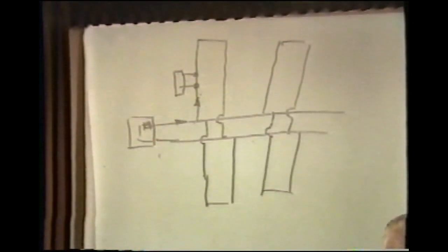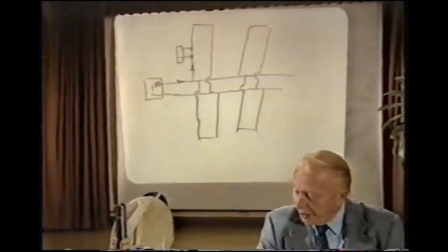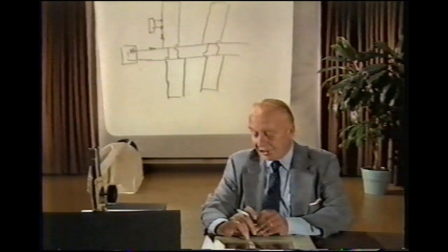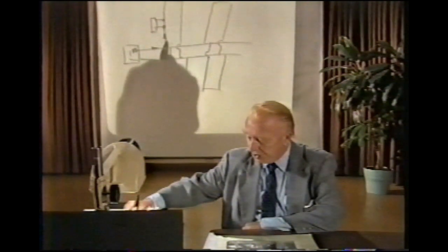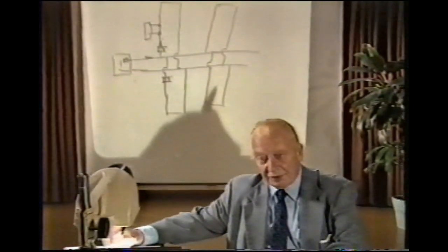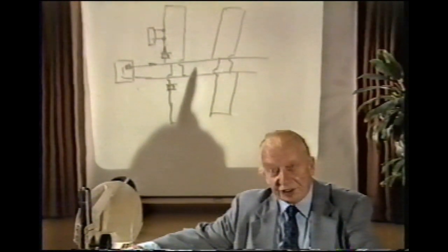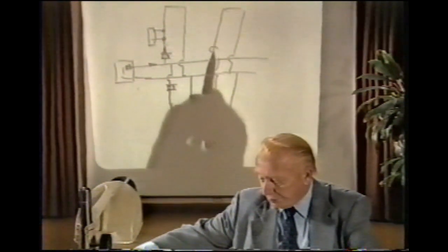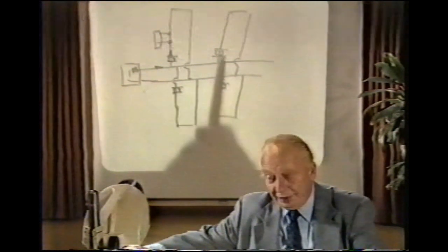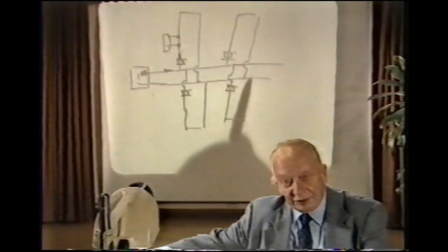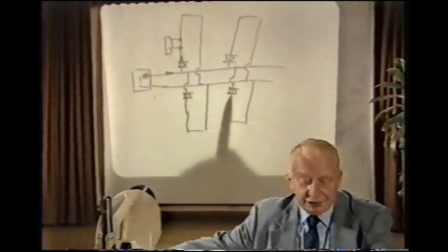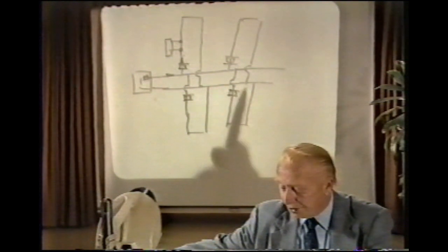Well, this developed into a very substantial problem. And the solution was very difficult, or we thought so at the beginning. Our first thought, of course, was to simply place extra pumps in each of these circuits so as to increase flow rate. But the building circuits were vastly different in terms of size, and it was soon determined that if we secondary pumped in this manner, what would happen would be that one of those large pumps would simply overcome the flow head characteristics of one of the smaller pumps, and we would have a very complicated, unworkable system.